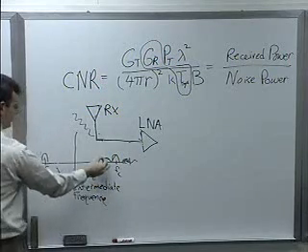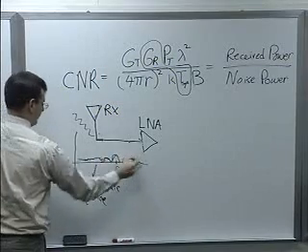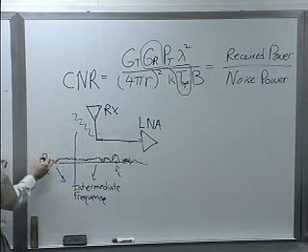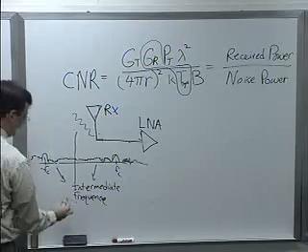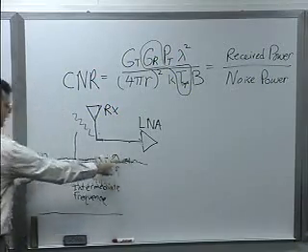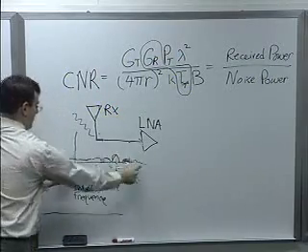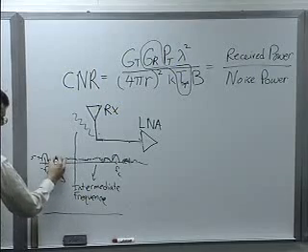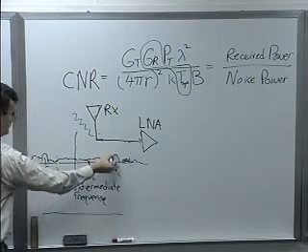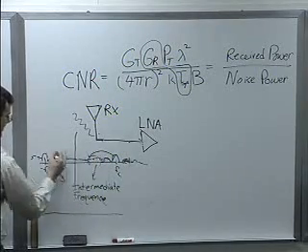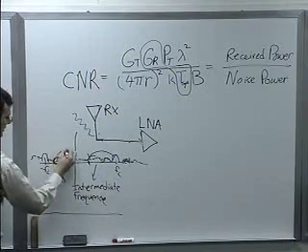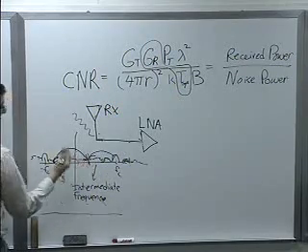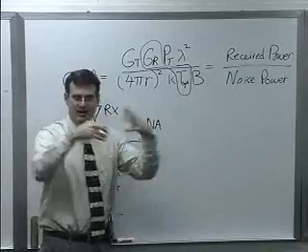So if you imagine there's a whole bunch of, say, harmonic stuff here. Let's just draw it all over the place. That's kind of how it is sometimes. And you mix this down by shifting copies of it down. Sometimes, if this is your target frequency, this is going to go down here. But then some of this frequency content here is going to go up here. And now they're both in band, and you can't filter it out.